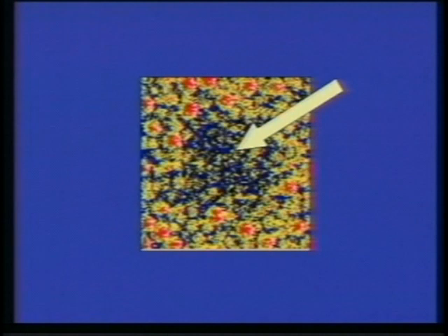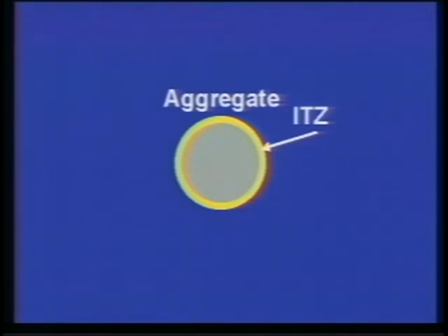Now 70% of the cement has hydrated. More black porosity and blue calcium hydroxide can be seen in the ITZ than in the bulk cement paste. The unique microstructure in the ITZ causes different material properties. The ITZ around a single aggregate is shown here. The width of the ITZ is usually about 10 to 50 micrometers. In concrete, the aggregates are so tightly packed that up to 1/3 of the matrix volume can be composed of ITZ regions. An important question is, do these ITZ regions percolate?